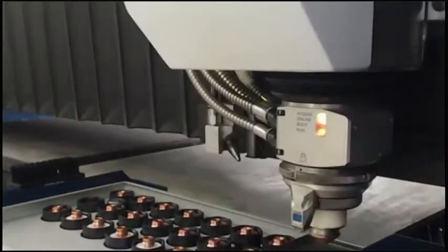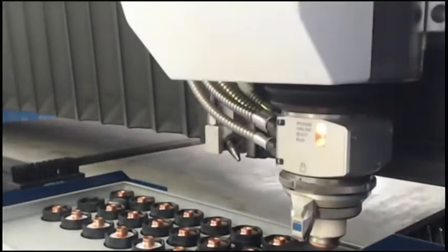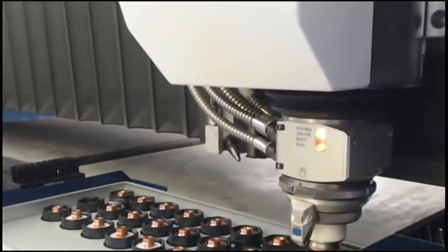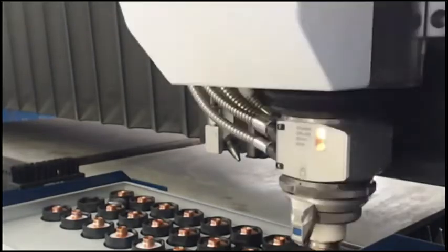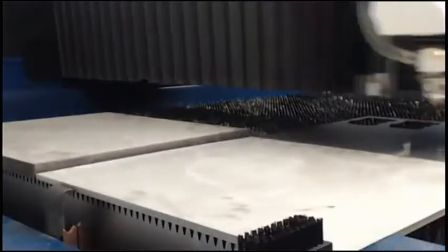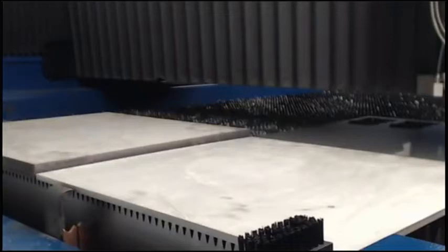It's a 21 spot changer. It's going to go do a control line calibration now. So that's basically our height sensing system. That's what we use to actually sense the sheet and know where it is so that we have the proper offset for our nozzle distance and our focus is always in the right spot.